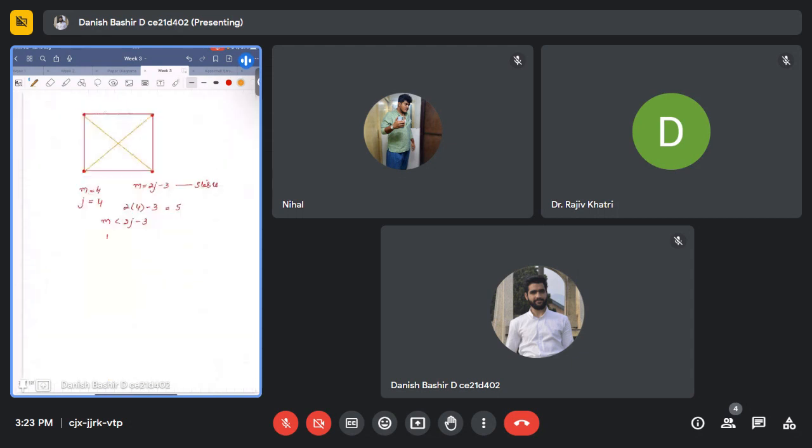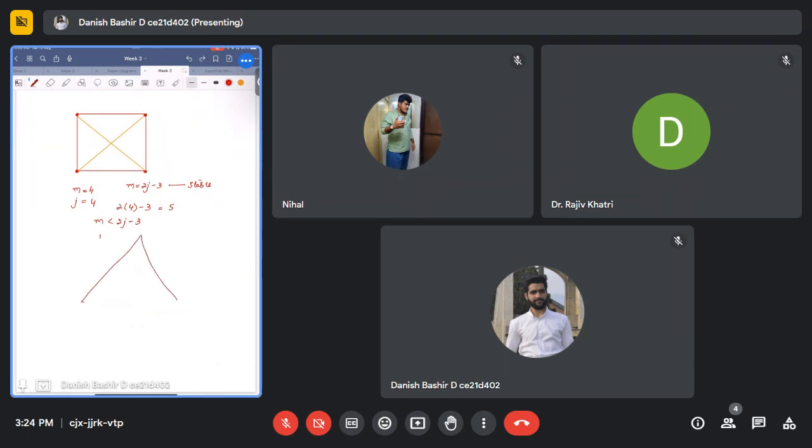I told you that for the triangular truss, we have M equals 3, J equals 3, and we got 2J minus 3 equals 2 times 3 minus 3 equals 3. So our M is equal to 2J minus 3, so it is stable. The same you will get in other types of structures.